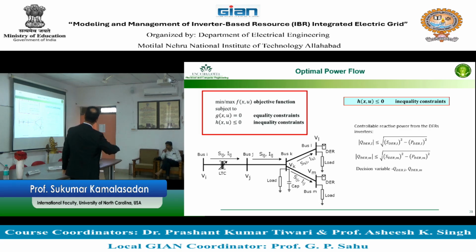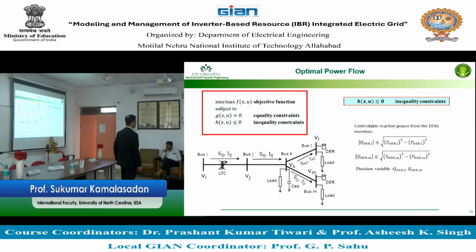So what you do is you try to develop an inverter decision equation based on a smart inverter. And what is the smart inverter equation that you can derive? You can say that the power from the DER is set by maximum power point tracking, pushing the power to the electric grid. Reactive power from the DER is changed based on the active power and the capacity of the inverter.